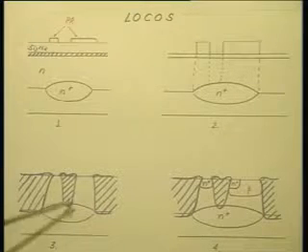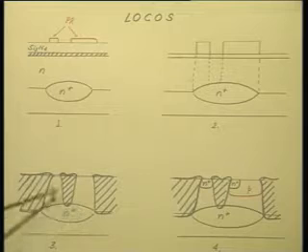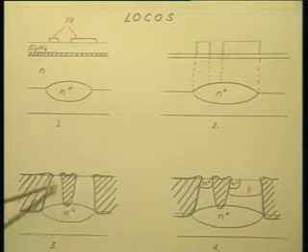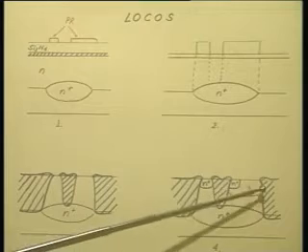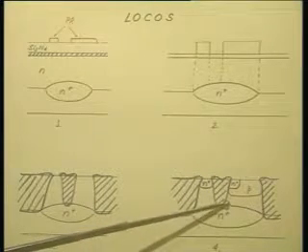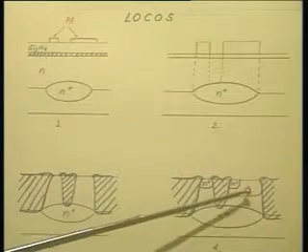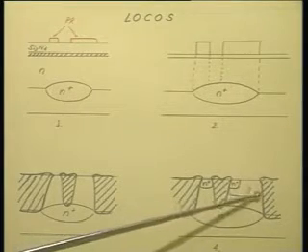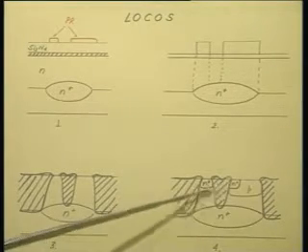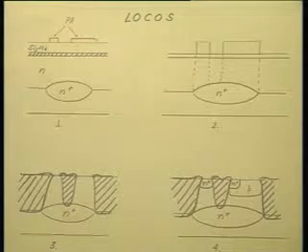Okay. So, you see this is your N plus buried layer, and on top of that you have realized these two regions. Now, in one of these, you carry out your base diffusion. Note a very interesting thing, the base now can be stacked against the two oxides on both sides.